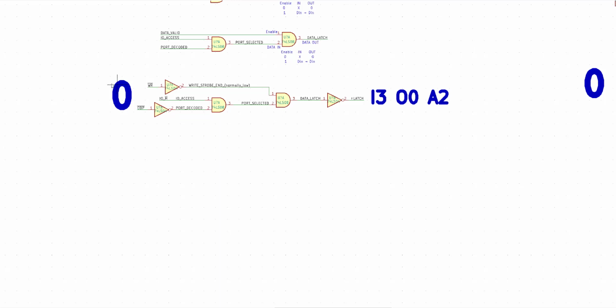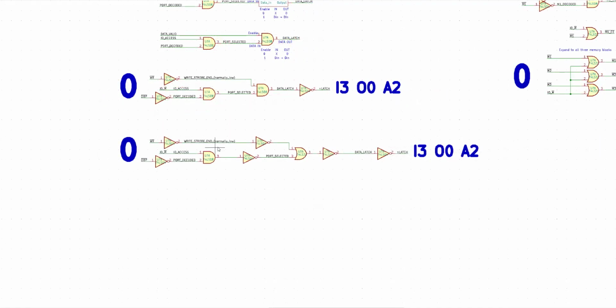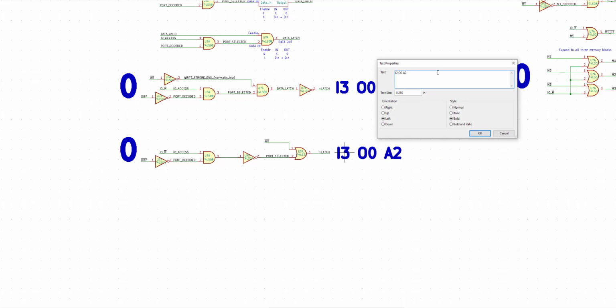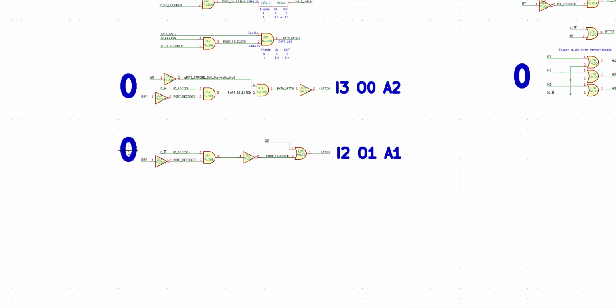Let me demorganize the second AND gate. So I'm going to make a copy of this. Okay, so that's been demorganized. Now I'm just going to simplify that by getting rid of both of these, and I have to get rid of this label in here because that signal is gone. That just becomes the right line. These are gone. That just becomes my latch signal. All right, and this has now 2 inverters, 1 OR gate, and 1 AND gate. And this is version number 1.